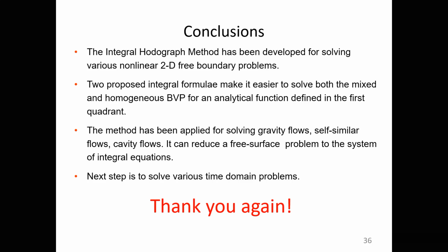The integral hodograph method has been developed for solving various nonlinear two-dimensional free boundary problems. Two proposed integral formulae make it easier to solve both the mixed and homogeneous boundary value problem for an analytical function defined in the first quadrant. The method has been applied for solving gravity flows, self-similar flows, cavity flows. It can reduce a free surface problem to a system of integral equations. The next step is various time-domain problems.